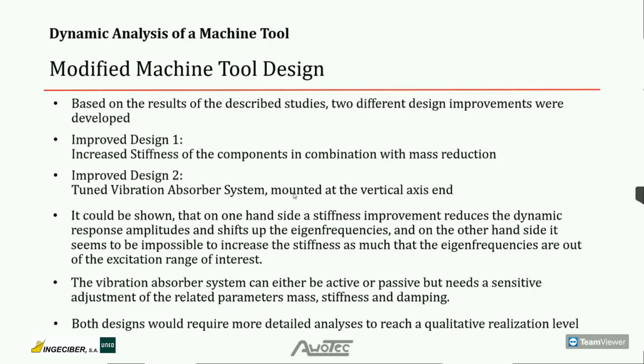It could be shown that the stiffness improvement reduces the response amplitudes as expected, and that with more effort, all the significant eigenfrequencies can be shifted out of the excitation range of interest.